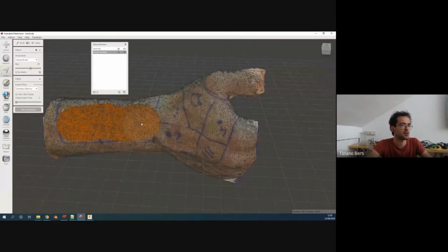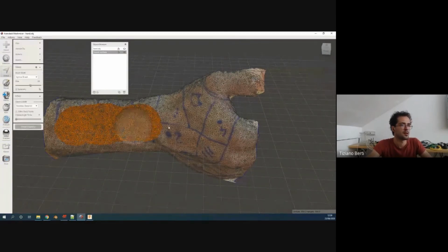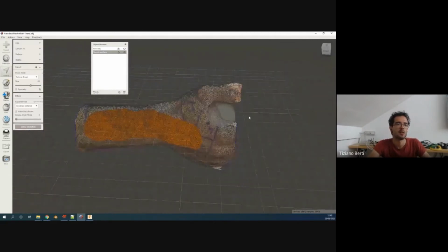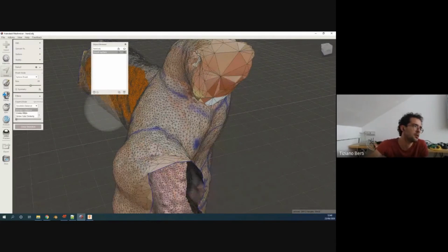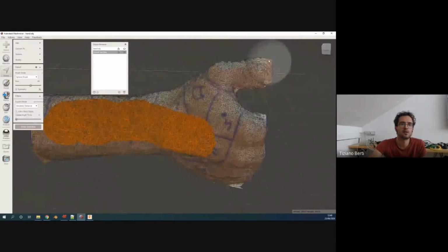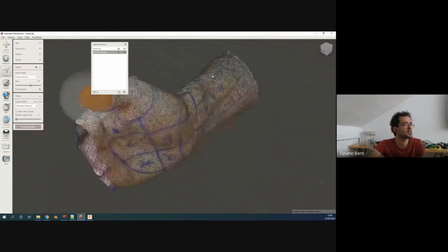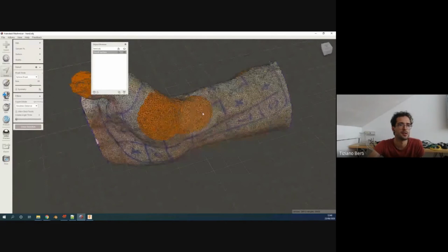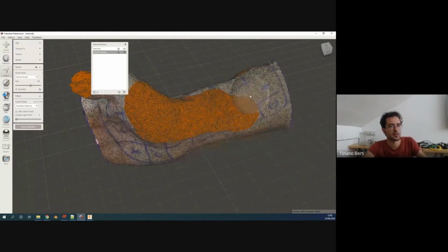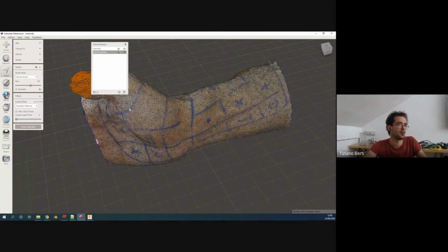So this brush is selecting just around a geodesic distance from the center point where there is the mouse. That means that this brush is turning around because it has this expand mode that goes like in the shorter distance around the object. So know that if you go like this, you're selecting also the backside part. Okay, so it's similar to a sphere, and it's not actually a sphere. With the control, you can deselect the part that we don't need.